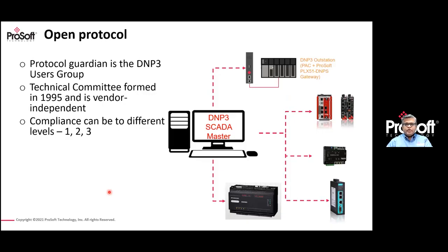The protocol itself has been open from inception. But a few years after the protocol was started, this technical committee was formed, and they've taken over to be the guardian. So it is completely vendor independent. And unlike Modbus, there is actually no variance of the protocol. They achieve that through a compliance requirement called the device profile document. Any product or solution that's DNP3 based has to create and release this device profile document.